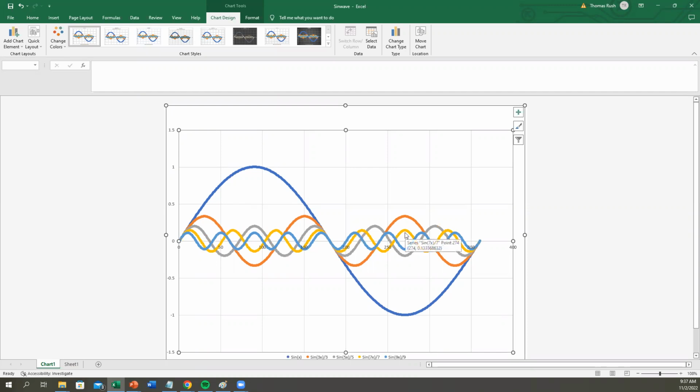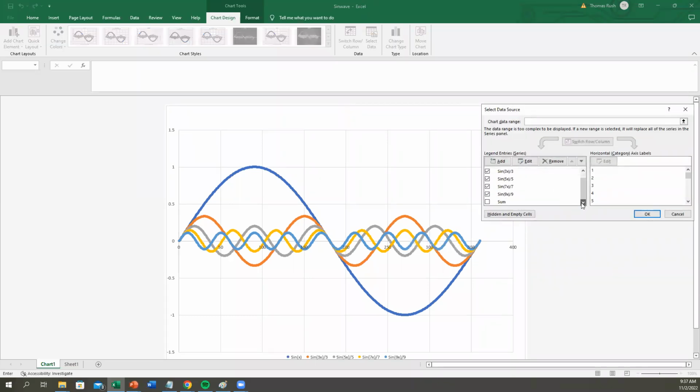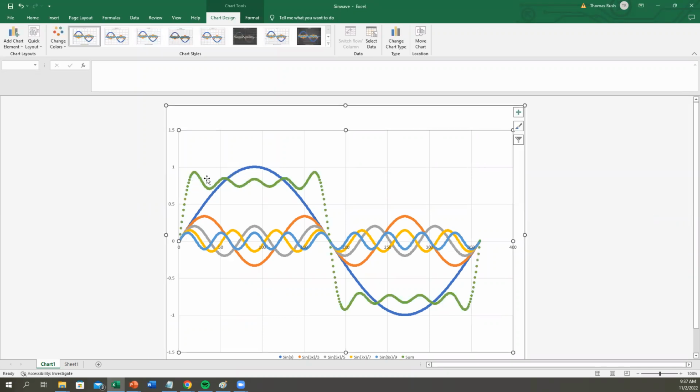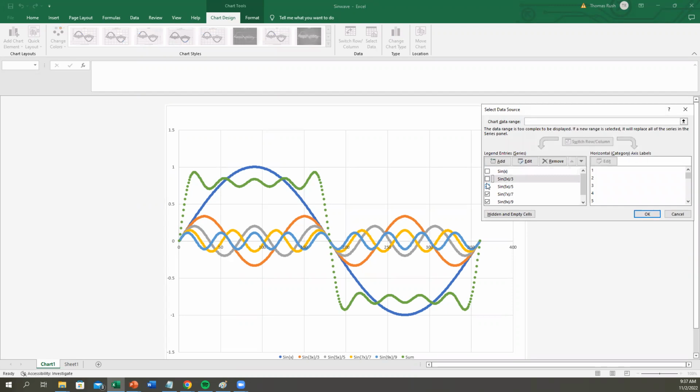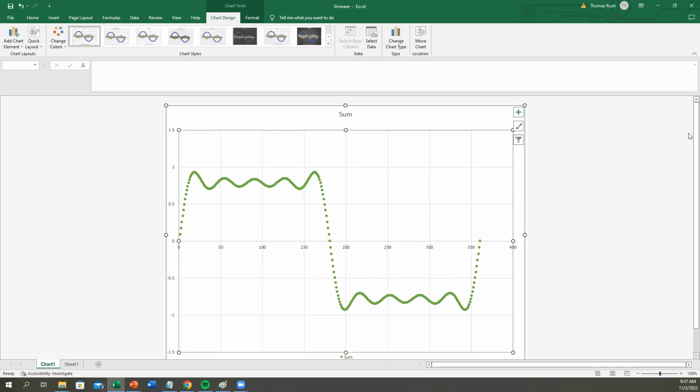Now, what the Fourier analysis says is we're going to add all these together. So it's the infinite sum of these is going to create that new waveform. And that new waveform, that summation, looks like this. So it's not perfect, but as we add more harmonics, this levels off and the steepness of the transition increases. So the summation of the first 5 harmonics gives us this, nearly a square wave. And so this is why we say square waves are rich in harmonics, because it's the summation of all of those alternate elements.